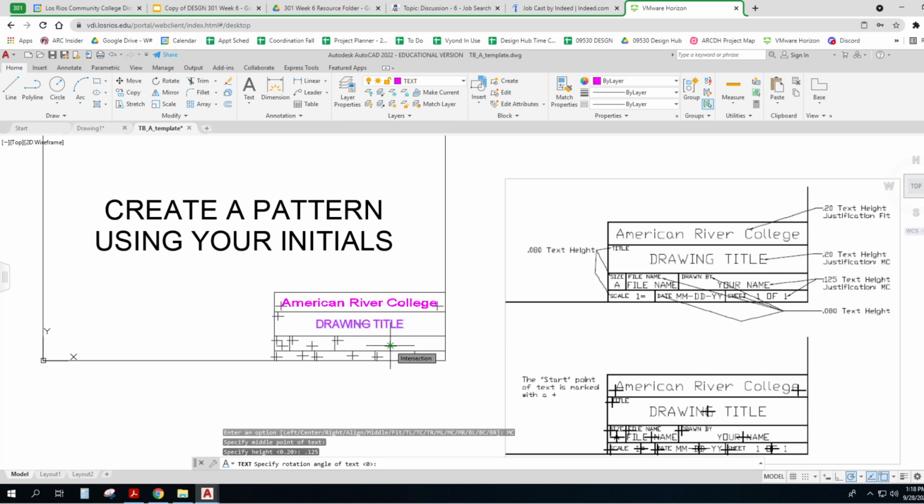0.125. Your name. Now, enter. You actually get to put your name in there, because this is going to be your title block. Now, all of these ones are 0.08. All of those ones are 0.08. And I think they're called justify left. So DT justify left.